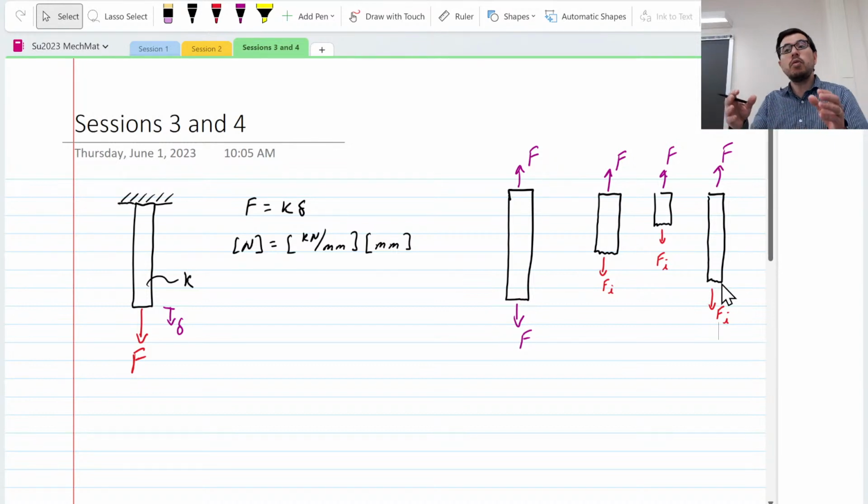And if that internal force is constant along the entire length of that member, then you can simply abstract it as a spring and figure out what the displacement is of that member in the system. That's one of the things we'll get at in the homeworks.